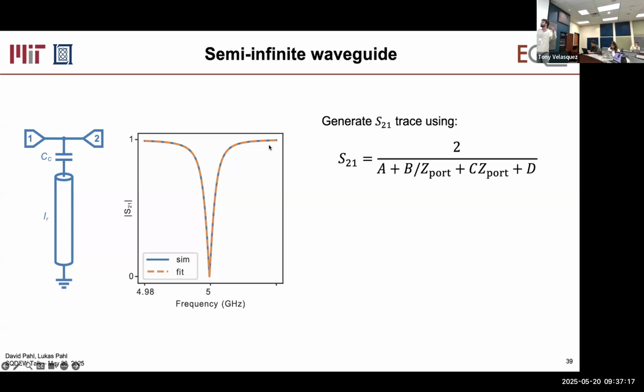I can give different answers to you, but one of them is the frequency at which this resonates, 5 gigahertz, that has a wavelength, right? That corresponds to a wave that's distributed in space. And a fourth of that wavelength fits snugly into this resonator, causing that wavelength to be trapped, to resonate, right? That causes all this behavior.